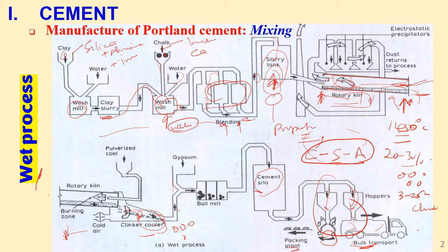So before we get cement, remember here from the rotary kiln, we have obtained clinker in pellet form. So we need to grind it to a very high degree of fineness. Before we do that, we add gypsum. Gypsum is hydrated calcium sulfate. Calcium sulfate, which is hydrated. I'll mention about that later on. But for calcium sulfate, this one will be required later on. That is required to reduce or to control the setting of cement.